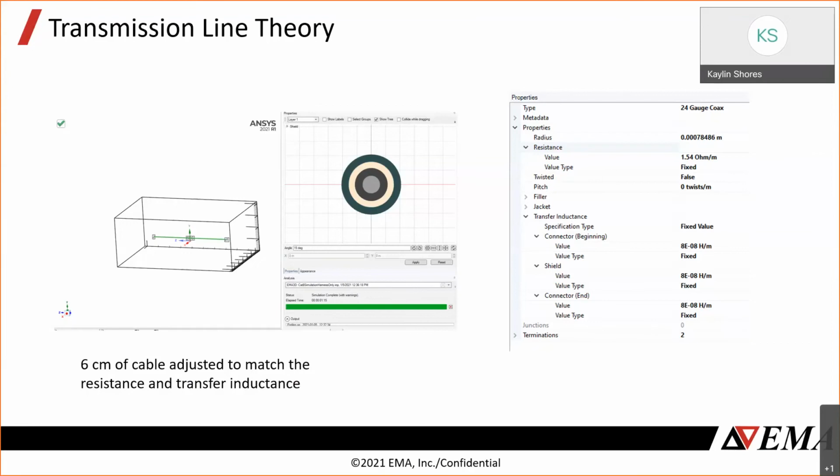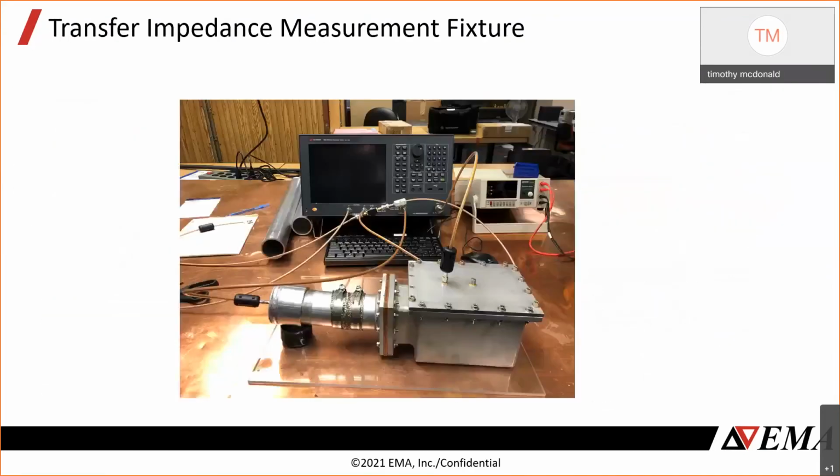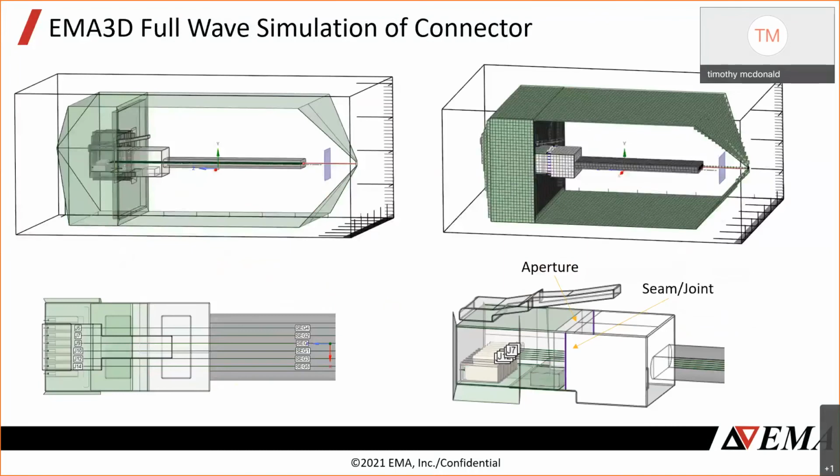Yeah, I am trying to remember off the top of my head the exact mesh resolution, but let's see. So that connector is just maybe 8 millimeters across, and it's got 8 cells. So it's probably on the order of 1 millimeter for this cell size, but we've dialed it down certainly sub-millimeter for connectors in the past. So mesh resolution shouldn't be a particular issue for that particular connector. I'm sure it's something we can get to the bottom of what's going on with it.